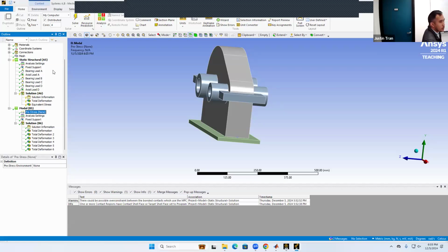If you remember, on Tuesday we talked about the string within tension. One of the factors that change the natural frequency in that string is the amount of tension within the string itself. The same thing is true for these mechanical parts. The internal stresses are going to change the natural frequencies within this part itself.